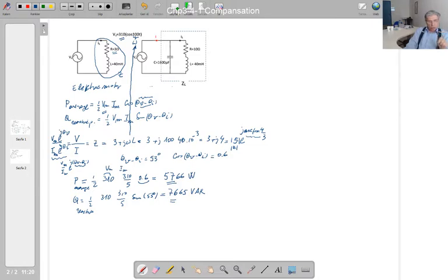But they do not apply this rule for houses, because in houses, the number of electrical motors is very limited. Washing machine and, isn't it, washing machine and refrigerator, for example, has a motor in it. So these are limited. The other electrical appliances do not have an electrical motor. It's a few of them, exceptions of course. So they don't charge for this reactive power that we consume in our houses, but they do charge manufacturers. Why is that? Because they use many electrical motors. Any energy that you require, you get from the electrical motor, electrical energy, and then transfer it to other energies in the manufacturing area.